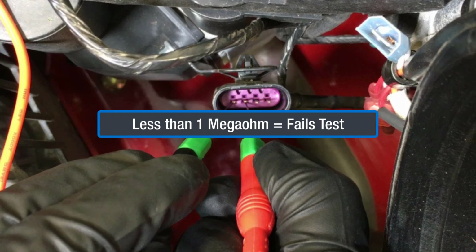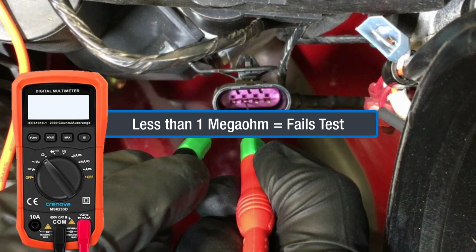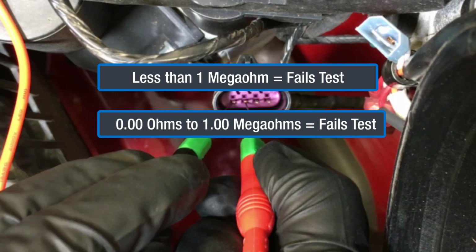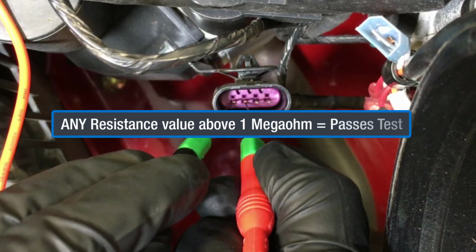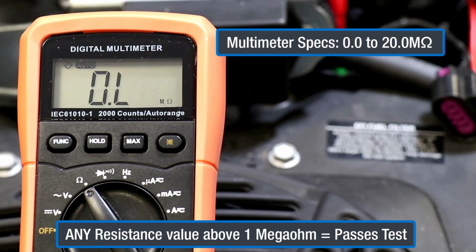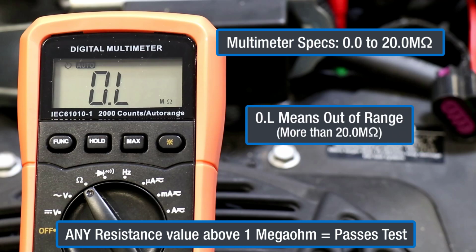Less than 1 megaohm is a failing test result, meaning any reading between 0 ohms to 1 megaohm fails the test. Any resistance value above 1 megaohm is a passing test result. The meter shown here can read up to 20 megaohms. Any resistance higher than that is indicated as OL because it's out of the meter's range of capability.